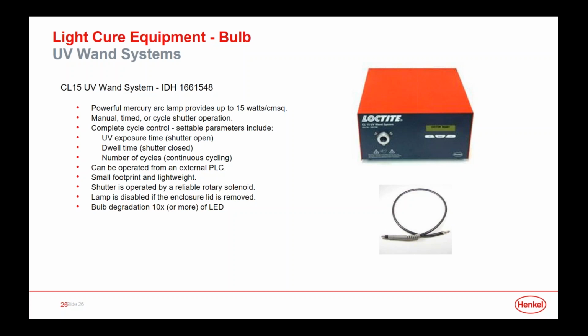As we mentioned before, the challenges with bulb technology with respect to LED is that they don't last as long, have higher energy consumption, and the bulbs have to be replaced more often. But they do serve a purpose because there are several adhesive chemistries in our product line that can't be cured with LED. So when you run into a solution where you can't cure a product with LED, you end up having to move to a bulb-based solution in order to deliver the proper curing.